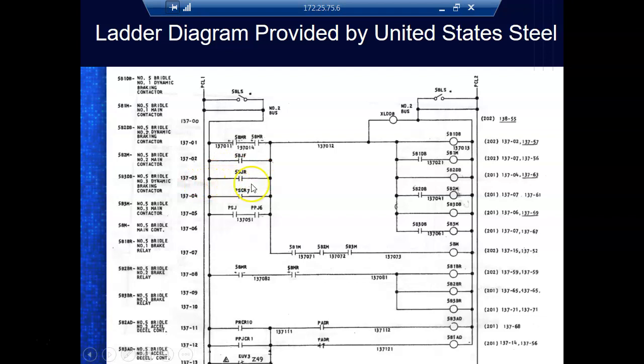So here's line 3. So this would be line 3, and this would be line 3. This is line 4. So this right here would be line 4. This would be line 5. This would be line 5. This does not line up with anything. So this guy right here is line 6. So line numbers go to the left of L1. We don't number rungs, we number lines. So a rung consists of one or more lines.